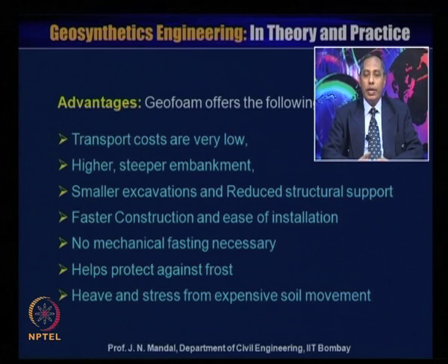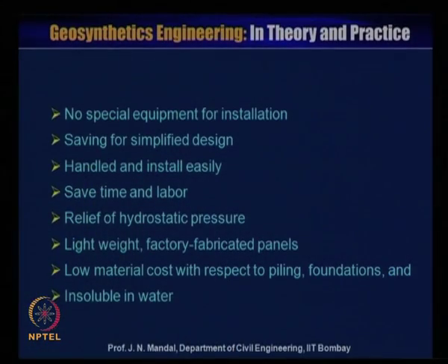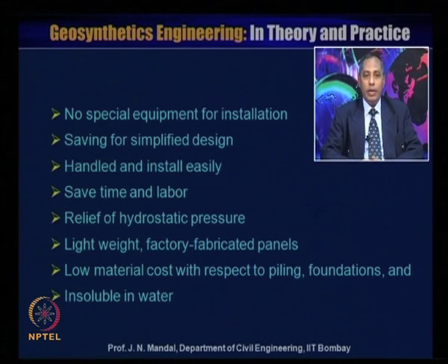No mechanical fastening is necessary. It helps protect against frost, heat and stress from expansive soil movement. No special equipment for installation. Savings from simplified design. Handle and install easily, save time and labor. So you don't need any skilled labor; unskilled labor can also install the Geofoam material. Relief of hydrostatic pressure.